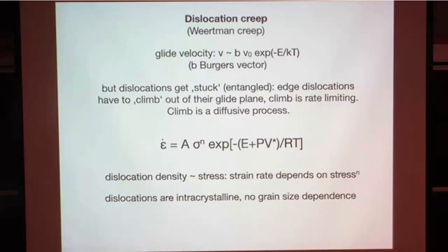This is a little bit the tension between these idealized models, which have been derived mostly from metals. Silicates are much different, right? You have the dislocation structures that tend to be more complicated, other processes at play. So in the end, we measure this exponent, and that's one of the fit parameters. So we do the experiments, measure the exponent, and that goes into this equation. So this equation is no longer the pure material science equation, that in this case, Weertman creep, for example.